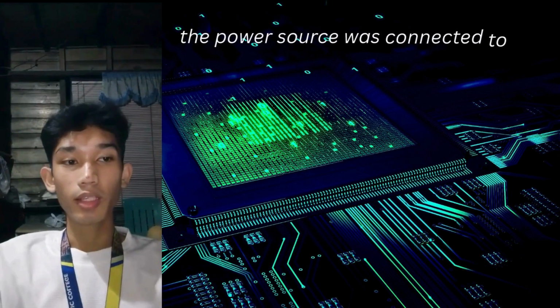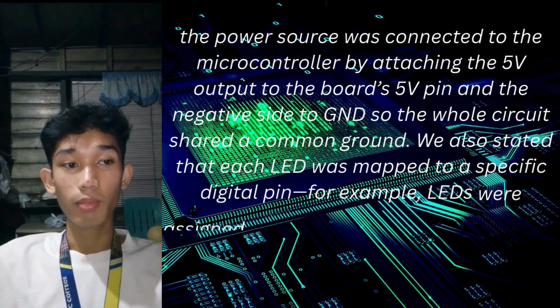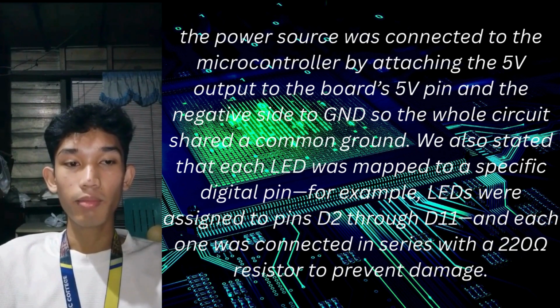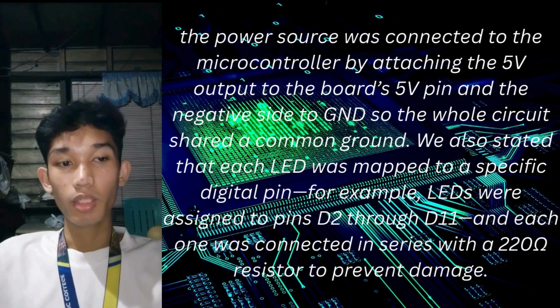The power source was connected to the microcontroller by attaching the 5-volt output to the board's 5-volt pin and the negative side to ground, so the whole circuit shared a common ground. We also stated that each LED was mapped to a specific digital pin.